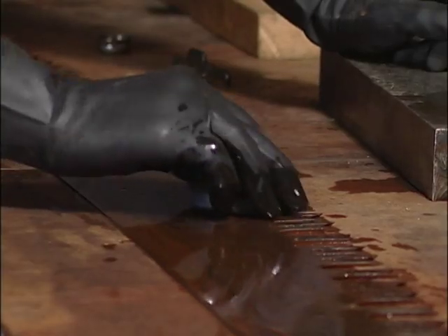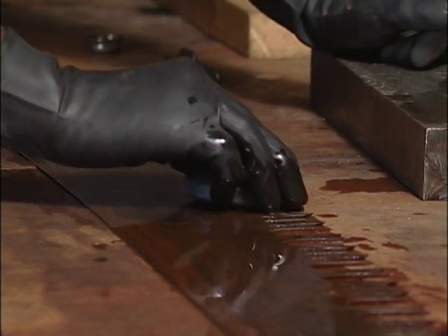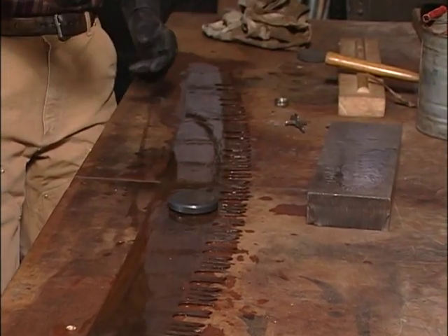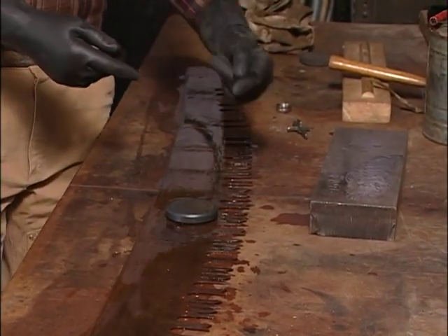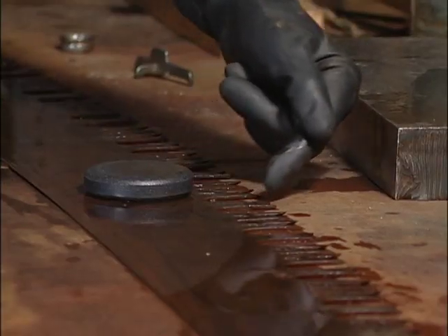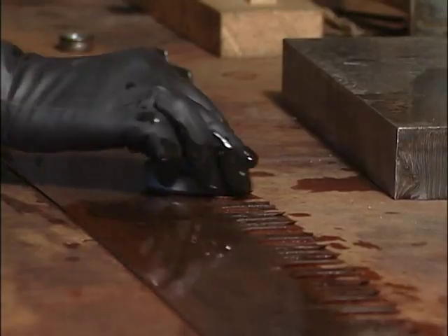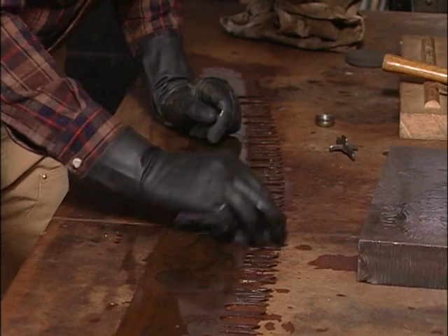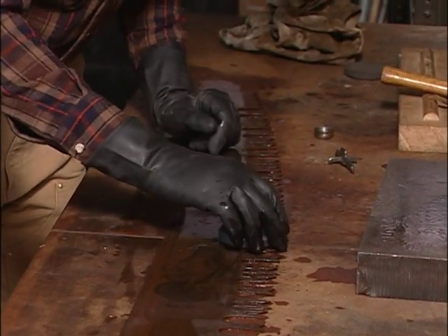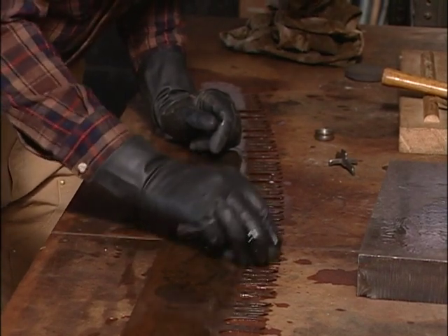Now clean your rakers quite well so that they're shining. And the reason for that is that a lot of these saws you'll have to heat treat later, and you can't do a good job of heat treating them unless you have a good shiny surface to watch the colors run. So you notice I'm keeping my fingers up on the stone, so there's no chance of getting my fingers mixed up with the tips of the cutter teeth there.